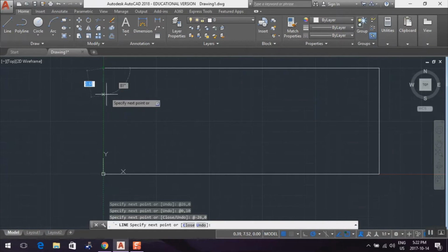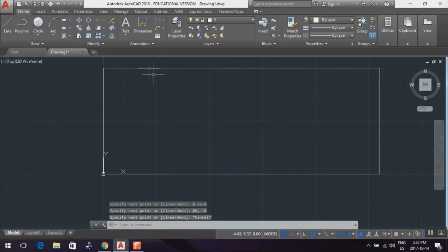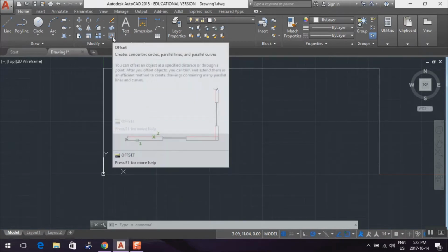I could bring this down here, and because 0, 0 is a point, I could click on it and snap to that. But let's go left and right 0, comma, we're gonna go down 10. And there we go. We have completed our rectangle. And now it's setting us up to draw another one. If we hit escape, it will get rid of that extra line that we're going to do.